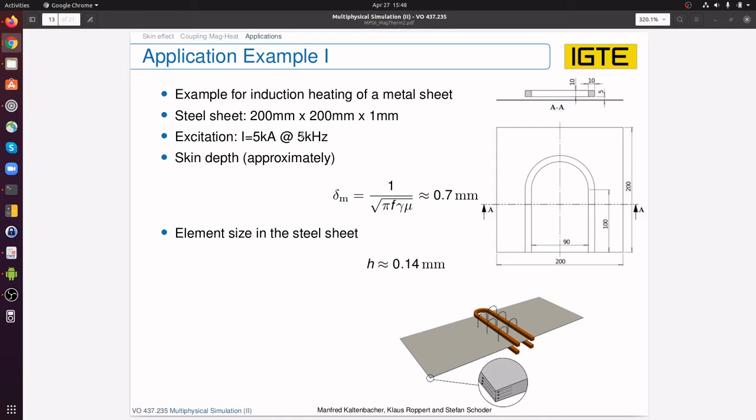So this is some kind of gray area that is actually following as a consequence of the different material parameters of the temperature. So temperature dependent permeability and also electrical conductivity, whereas electrical conductivity has a little bit minor influence than the permeability, but they do couple back into your electrical circuit.